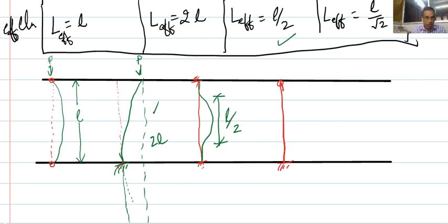Now, if you look at the buckling behavior of this column, whenever there is a hinge, the buckling starts from there, and whenever there is a fix, buckling ends somewhere early, something like this. So practically buckling started somewhere here and goes up to the end here. This length we call L by root 2, which is nothing but 0.7 times L. This is 0.5 times L, this is twice L, this is L. This is what the effective length means.